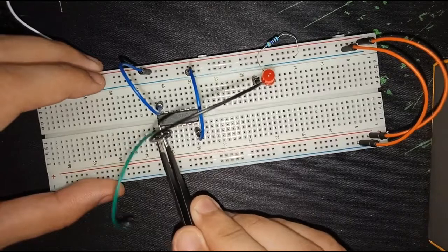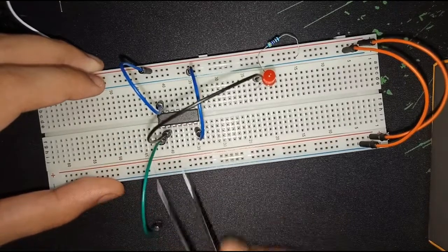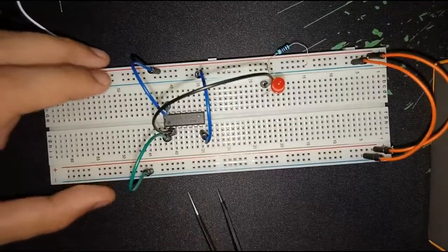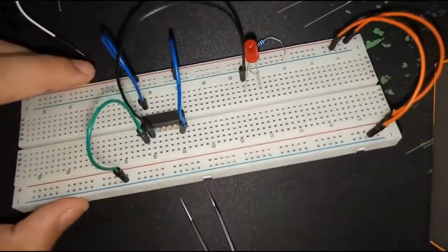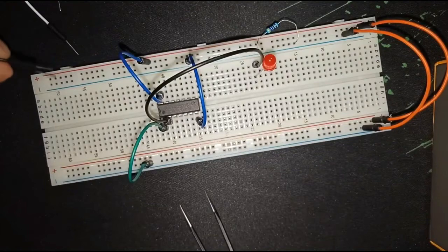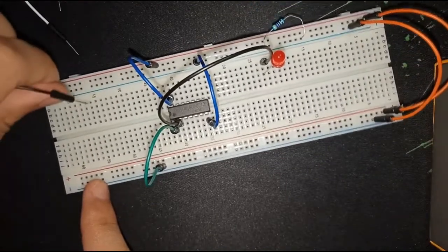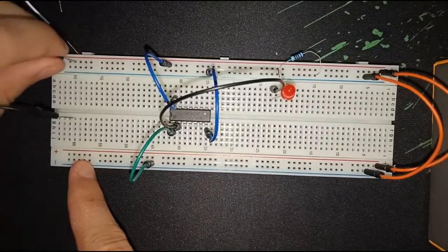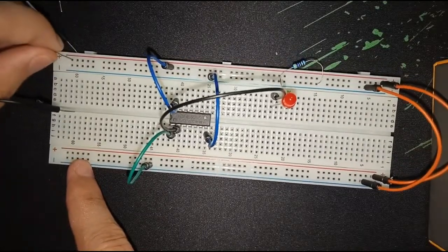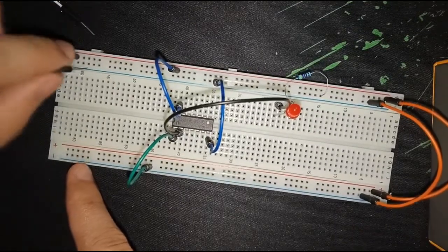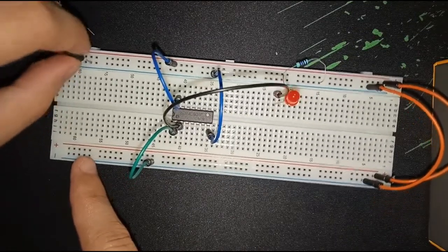So for now, connect it to your negative ground, or 0 input. So therefore, if you input 0, then it outputs 1. So meaning, it lights up. So we will connect the battery, so we can see if it is correct. So input the positive and negative from our battery.